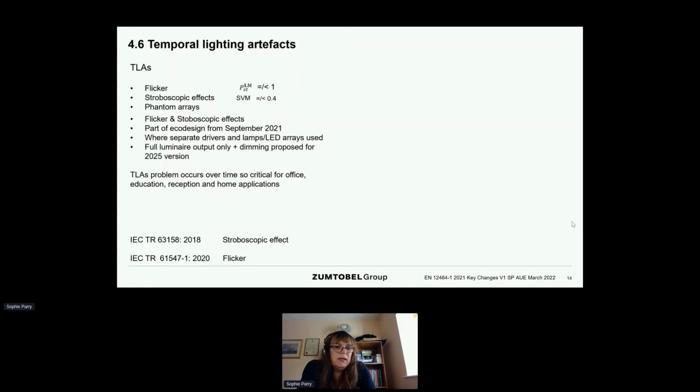And then LED lighting came along, and the problem started to reappear again with certain LED luminaires. And people said, well, you solved this problem with fluorescent and you introduced HF ballasts. How hard can it be? Well, actually, it's not that simple. A HF ballast had a 230 volts AC mains input and also gave 230 volts AC output usually. So it was AC in, AC out at more or less the same voltage. So the engineering required in the ballast to solve the problem and the high frequency conversion was very different to the engineering that you would need to apply to an LED driver.